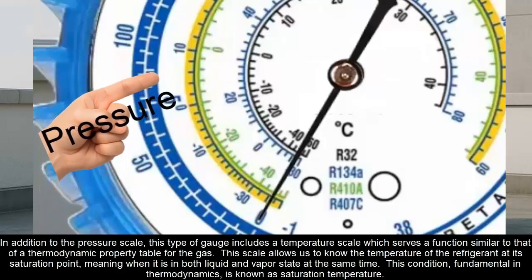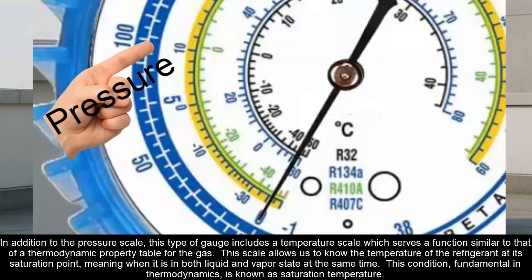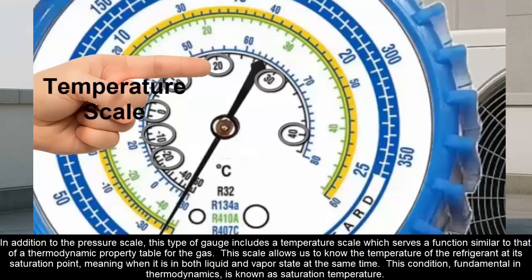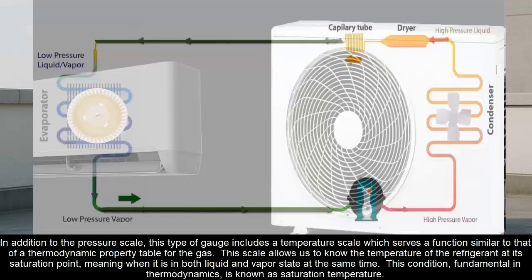In addition to the pressure scale, this type of gauge includes a temperature scale, which serves a function similar to that of a thermodynamic property table for the gas. This scale allows us to know the temperature of the refrigerant at its saturation point, meaning when it is in both liquid and vapor state at the same time. This condition, fundamental in thermodynamics, is known as saturation temperature.